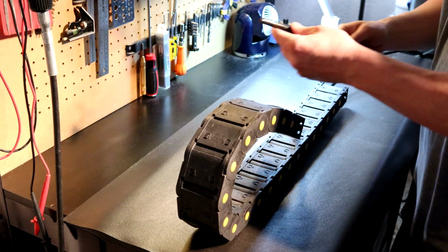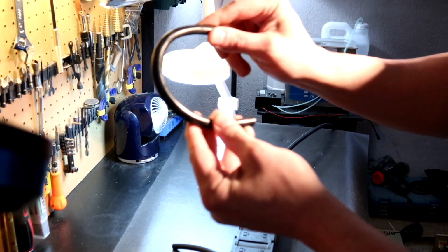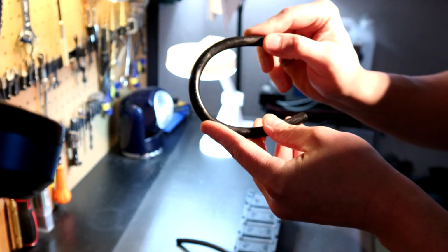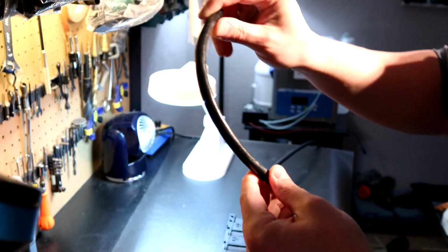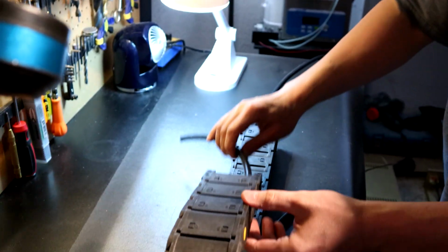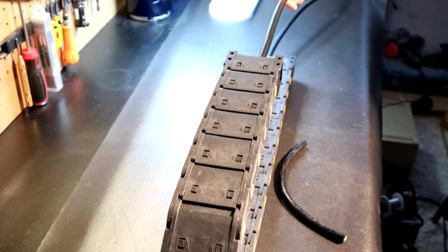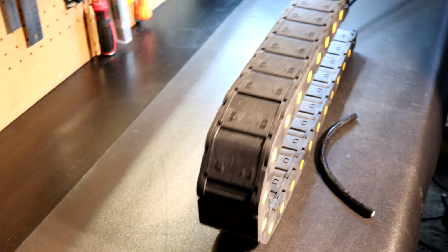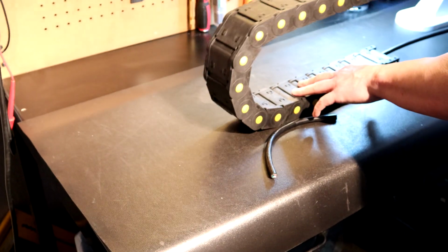Now I have a smaller piece of my cable right here, and you want to see, this would be about your maximum bend radius. Would I recommend anybody be at this bend radius? Absolutely not. You always want to leave a wider gap. What I like to do is let the cable relax. If you let the cable relax in the chain, you can see it finds its own arc, because that's where gravity's pulling it. And again, the actual cable's on the bottom, everything is set.